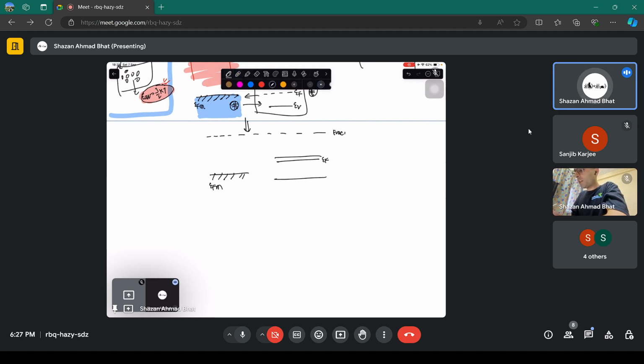So this is called the work function of a metal. The work function of a metal is the energy which you need to give for the electrons to jump to the vacuum level, to make them totally free from the force of attraction of the atoms. And this is called the work function of the semiconductor. It is measured with respect to the Fermi level because that is the highest energy level of the electron. The Fermi level is the highest energy level of the electron. Okay, that is basically the definition of the Fermi level.